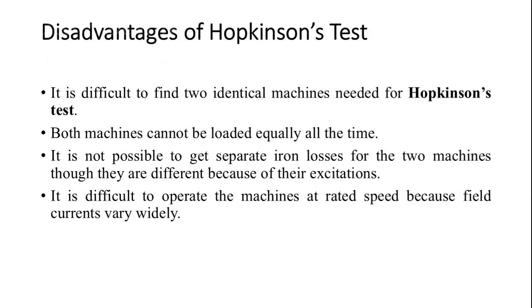However, Hopkinson's test has its challenges. Finding two identical machines is difficult, and they cannot always be loaded equally. Separate iron losses for the machines are hard to obtain, and operating at rated speed can be challenging due to varying field currents.